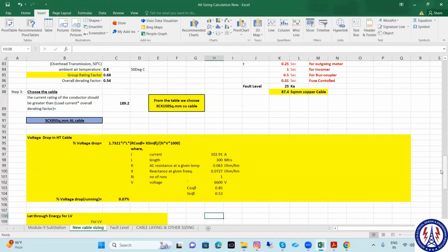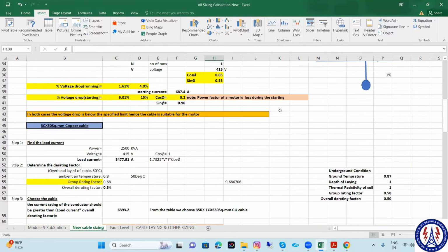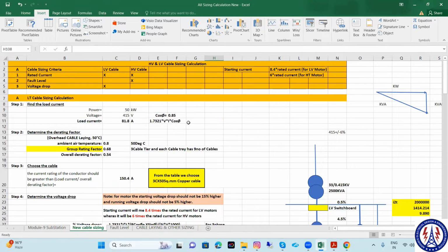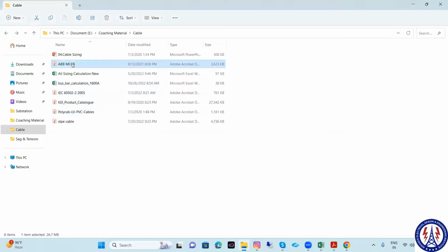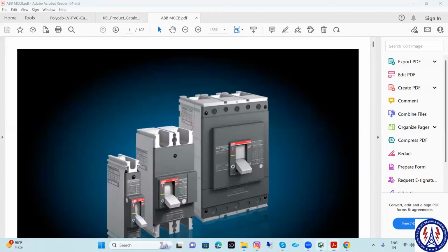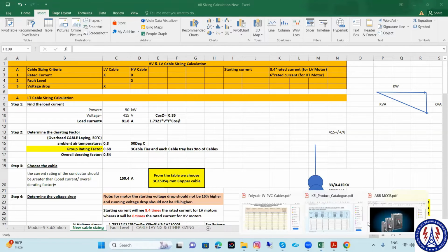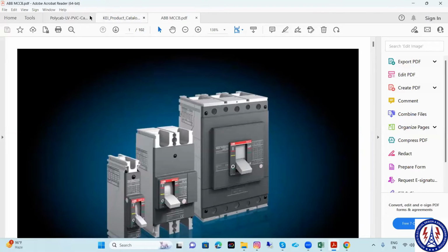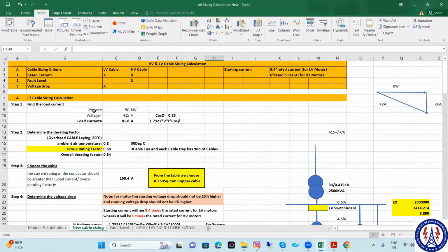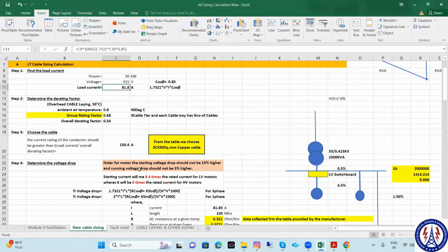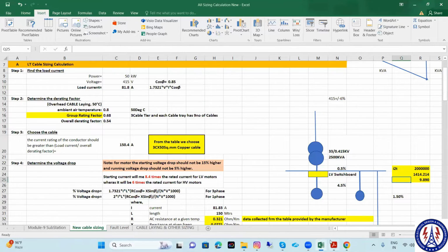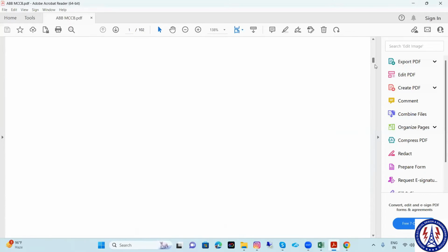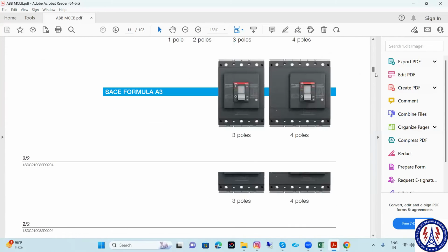Okay. In the LV, I was avoiding the minimum cross section fault level. In the LV, as you know, we are using the MCB or MCCB, right? The MCB is a current limiting device. The meaning of this is, this is the catalog given by the vendor. For the 50 kilowatt, suppose I am selecting an MCCB of 125 ampere based on this current. So I will go to the catalog: 125 ampere MCCB, 50 kilo ampere fault.